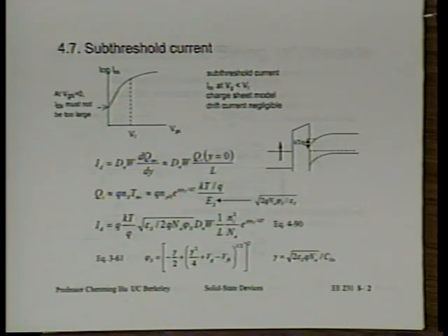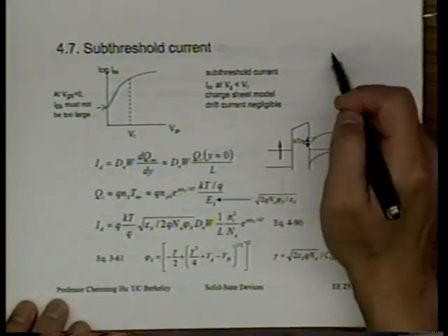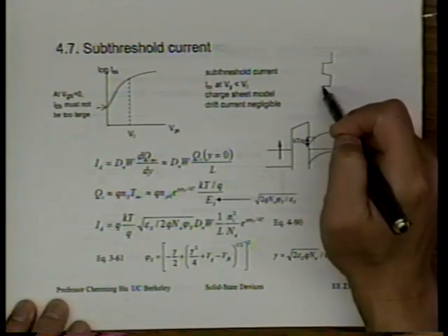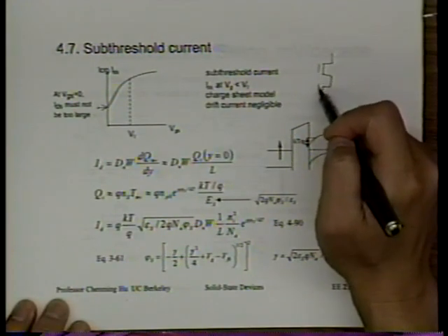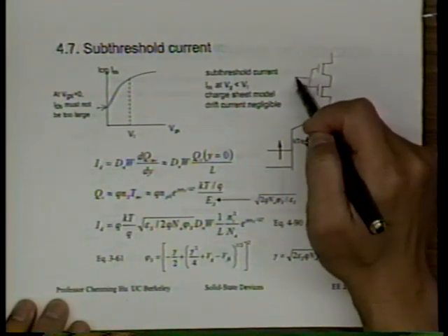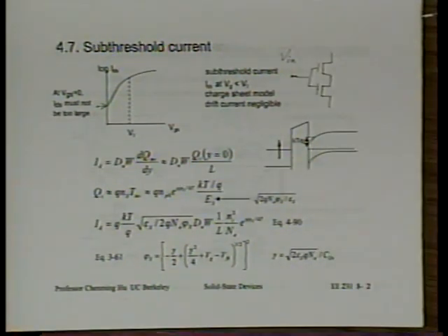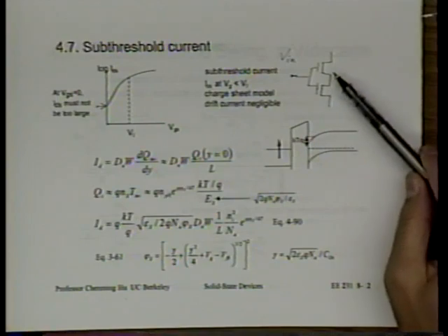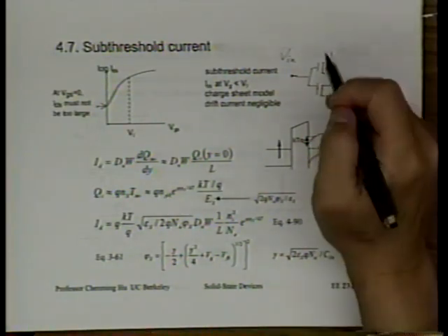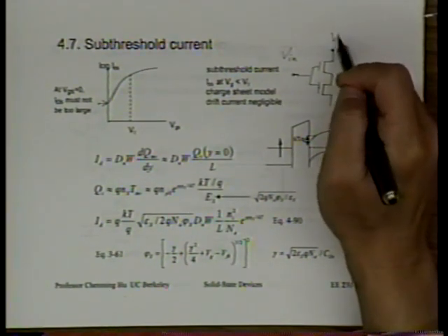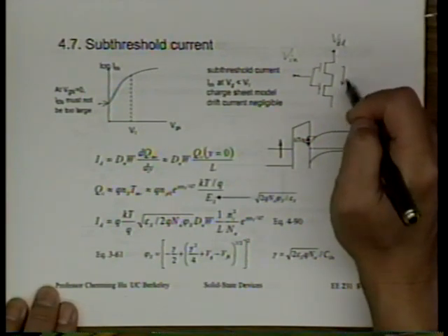Now, why is that? Because in a circuit, suppose a CMOS circuit, let's say, one of these two, it doesn't matter whether this V in is equal to high or low, one of these two transistors is in the off state. Because it's in the off state, there's no current flowing between VDD and the ground.